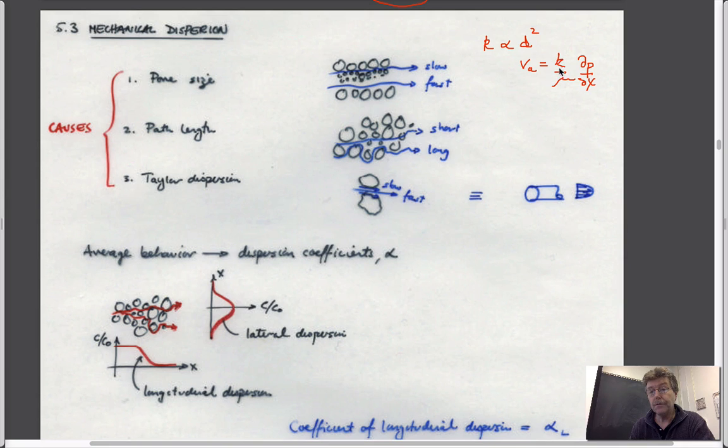If permeability is low, then advective velocity will be low. If permeability is high, it'd be high. And so if you have pathways through small pore throats, it'll be relatively slow moving. If it's going through fast pore throats, so if you start the races with a particle here at time t0 and look where it is 10 minutes later, if it's going slowly, it'll have gone half as far as a particle that's traveling twice as fast. And so you'd expect to get a distribution of two different fronts that have been separated as it goes through it.